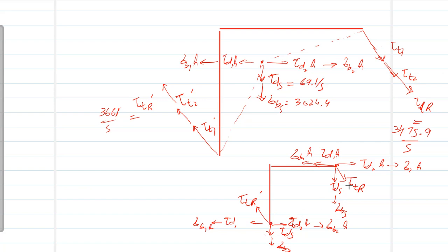Now see, there are two points in which you have to concentrate all the vectors. From now onwards you have to sum these to find the resultant. Now as you can see in the diagram, this resultant is in the direction of the direct shear and the torsional shear, which certainly means that its component will be added. Whereas if you look at this tau r prime, its vertical component is subtracted, which you can assume even in the exam, that at this point the overall stress will be smaller.